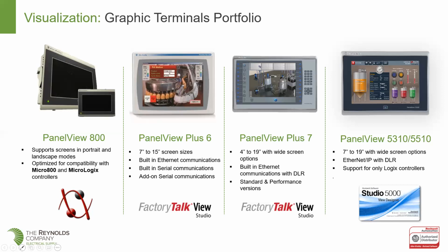And they will use the Connected Components Workbench software to develop the screens. So it's a good product, and we'll show a little bit of the architecture of that in a minute. It's designed to be the lower cost alternative. They come in 3 sizes: 4-inch, 7-inch, and a 10-inch panel. Color and touchscreen, and they have Ethernet and a serial port on them, so it gives you somewhat decent connectivity options.